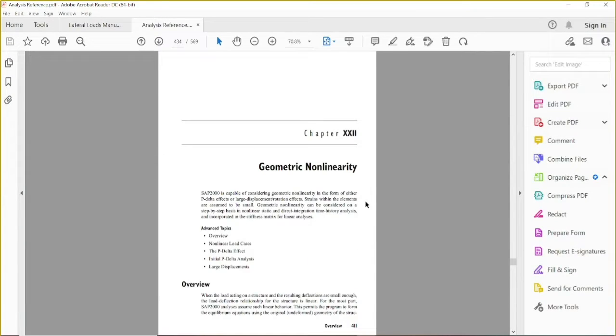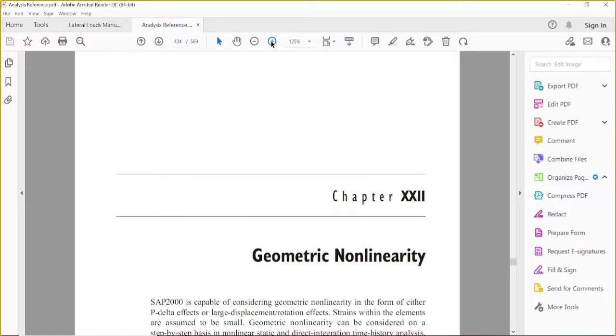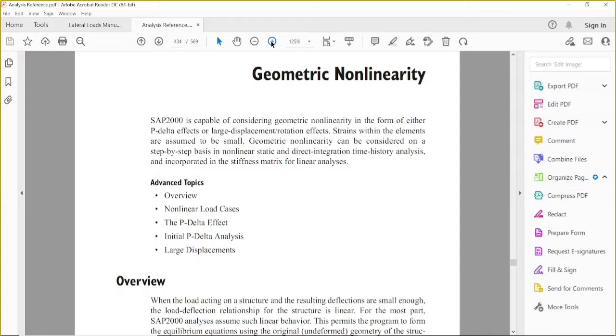When discussing this, it comes under geometric nonlinearity. If all the members are linear and behave linearly, then the P delta effect is not required. Practically, if you want to know the nonlinear behavior after the elastic stage, how the member behaves, generally in tall structures within elastic limits, you can study the P delta effect.